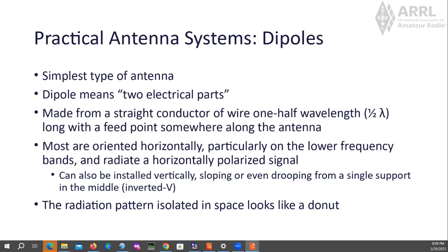It radiates in all directions in the vertical frame, and it radiates in a figure 8 pattern in the horizontal. However, just because the end of your dipole is pointing at a station does not mean you can't work it. It just means that it won't have as strong a signal because of the way it's oriented.